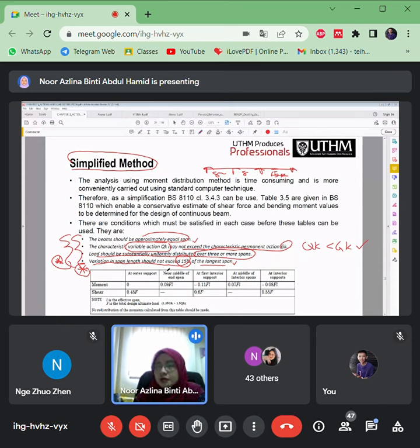So how to use the equations of this table is quite simple, but you need to understand the locations for that moment here. It gives moment and shear equations here. It mentioned here at the outer support, moment 0. So the outer support, the very last one, and the support moment is 0, of course moment 0. I'll try to change color.